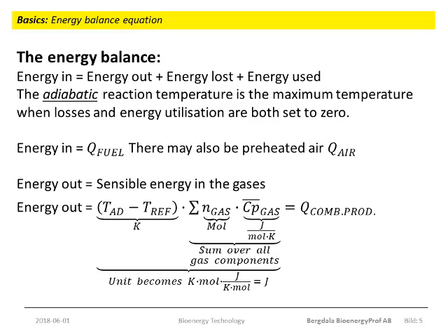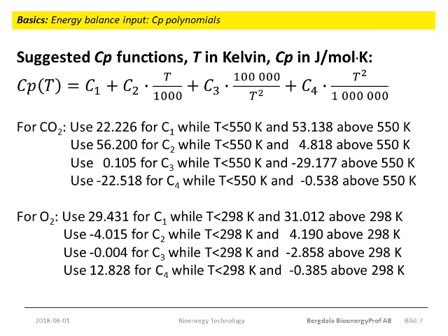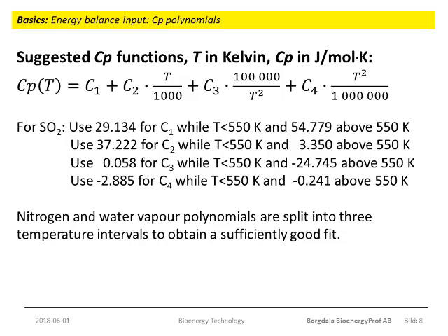So the expression becomes simple enough, but what complicates things is that the Cp values for gases are generally strong functions of temperature. The diagram shows functional approximations for the Cp values for the actual gas components in joule per mole and degree, as a function of the temperature from 0 to 2500 degrees C. There are other functional approximations available, but I use these for temperatures above 0 degrees C and up to about 2000 degrees and at atmospheric pressure.